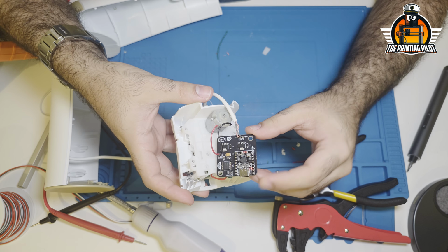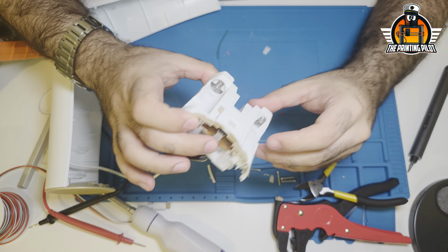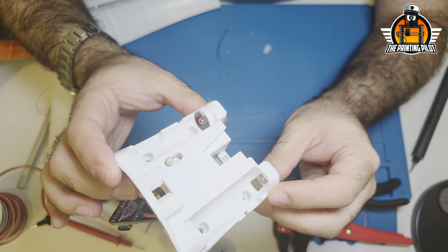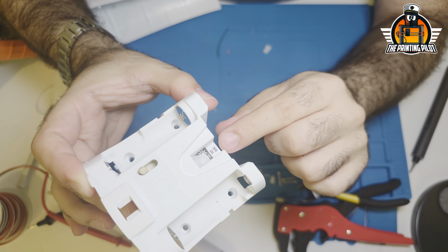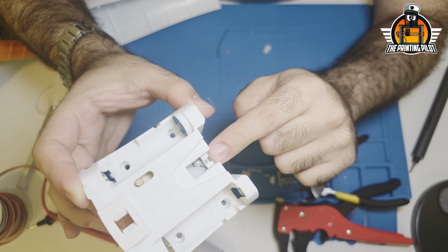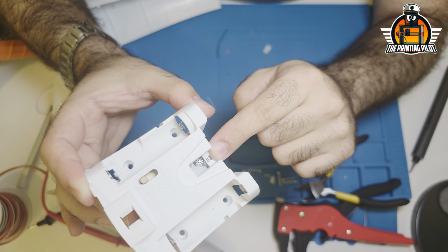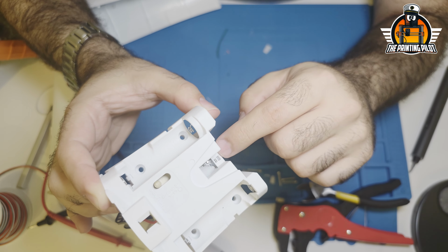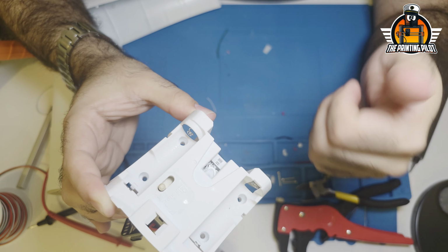So after connecting it to the power, making sure the LED is on, we're going to press the button once, and then we're going to watch the motor. I'm going to press it, and we're going to hear the motor spinning. We're going to hear it spinning once, going down, and then spinning the second time and going up. That is the desired result. If the motor is spinning the wrong way, first up and then down, then you'll have to replace those leads or change it in software. But we are all good.